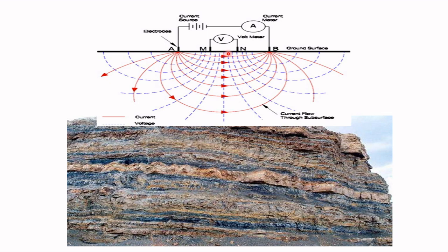In any homogeneous medium, we say that apparent resistivity depends on the geometry and the resistivity of the elements that are given in the geological medium, and it does not represent any average resistivity. It can be a lower value and also a higher value. So when the current is passing deep inside, the apparent resistivity value will change. Based on that, we will be plotting different graphs and then finding out the geological strata or groundwater, or we can identify the minerals.